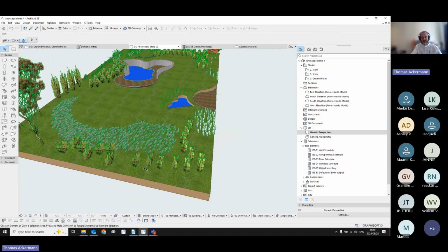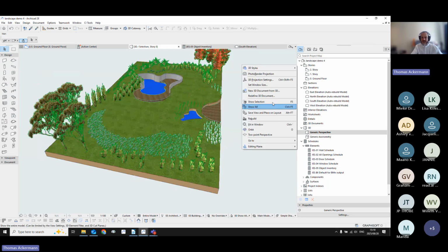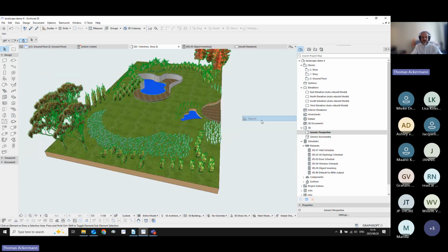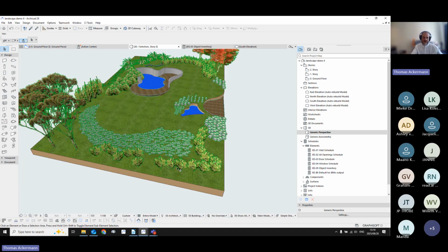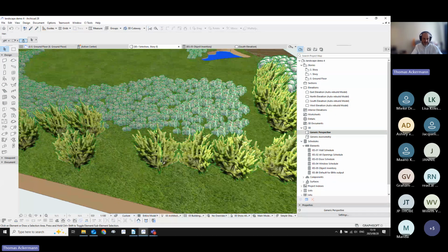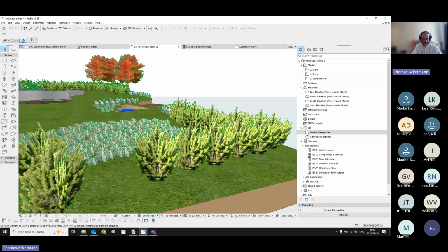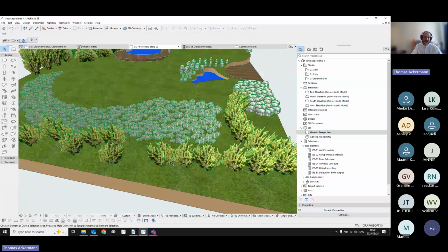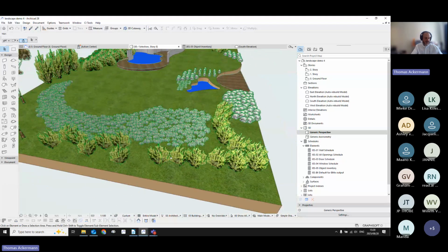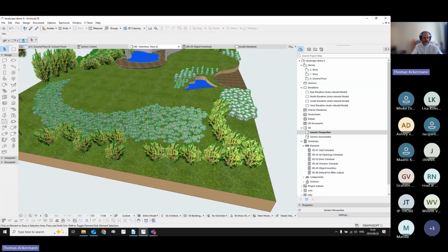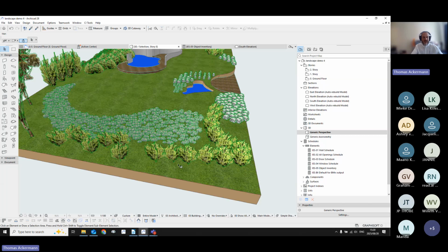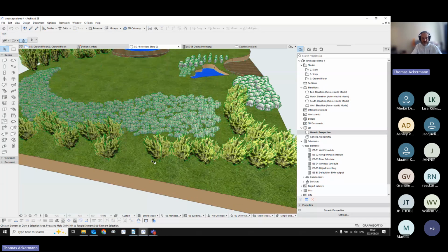And if I want them to face me, I can just rebuild this 3D view, and the 2D aspect of all the plants will show to me. You can also see that there's a secondary part to it that will always point to the sun, because we've indicated that we want these plants to cast a shadow, and that shadow is generated by a secondary polygon.